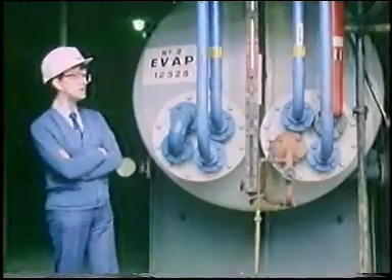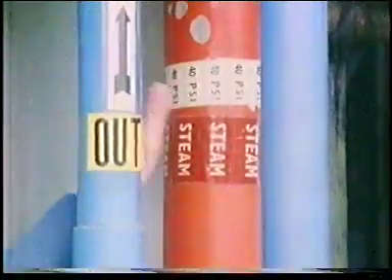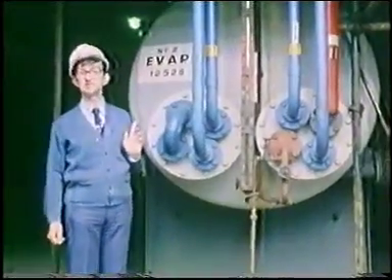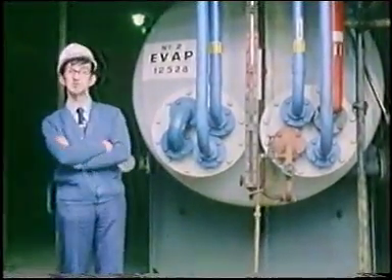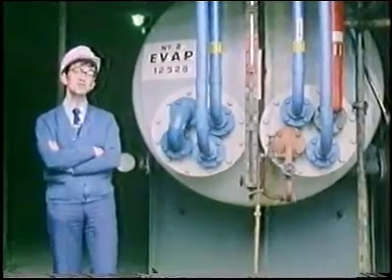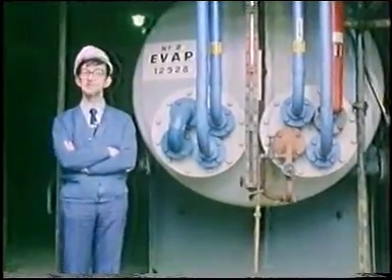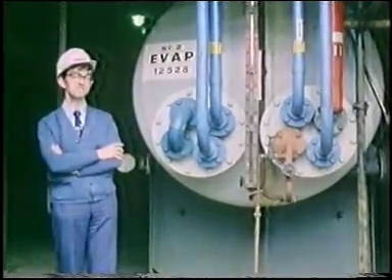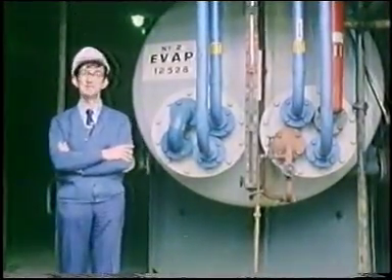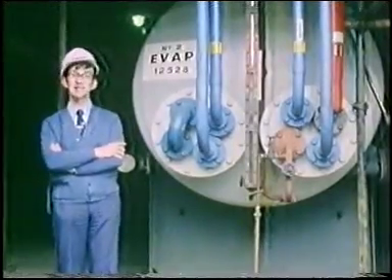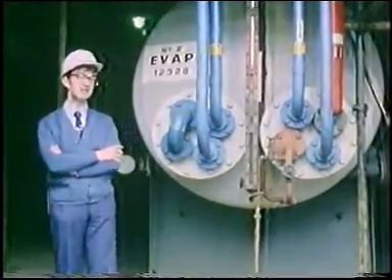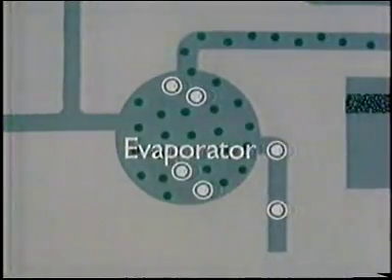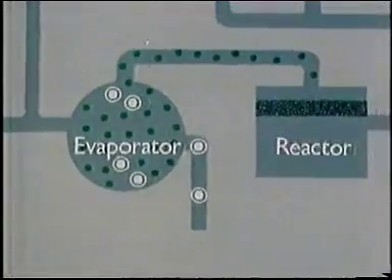What we do down here is to heat the evaporator with steam, and water pipes cool it down. And the use of these 2 is very important in careful temperature control. You'll appreciate what I mean when I tell you that a 1 degree rise in temperature down here can mean a 16-degree rise in temperature up in the reactor. An upper limit is set for safety, and if the reactor temperature exceeds that limit, then the air supply is automatically cut off. So the ethanol is vaporized in the evaporator and oxidized in the reactor.